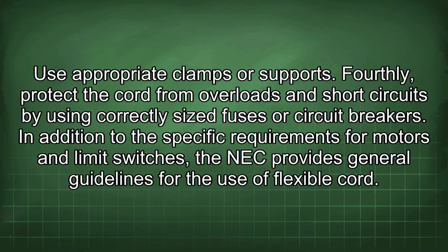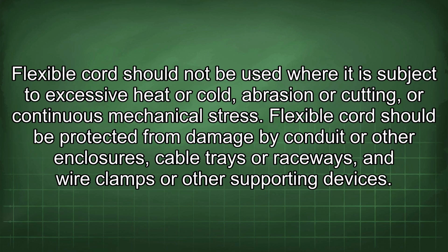In addition to the specific requirements for motors and limit switches, the NEC provides general guidelines for the use of flexible cord. Flexible cord should not be used where it is subject to excessive heat or cold, abrasion or cutting, or continuous mechanical stress. Flexible cord should be protected from damage by conduit or other enclosures, cable trays or raceways, and wire clamps or other supporting devices.